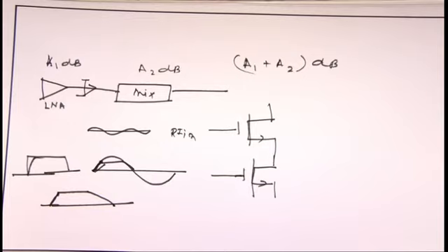So in a large signal model, suppose you have 300, 400, 600 millivolt peak to peak, it will also behave like a switching one with a finite rise and fall time, which will be there in your output spectrum. What I am saying is that if I go for a rectangular or square kind of LO, with a very fast rise, I am expecting all the odd harmonics.